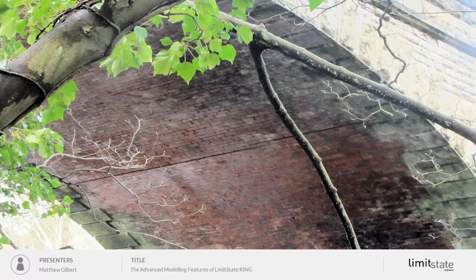but that's largely down to my assumptions on the level of backing in the bridge, and if I adjust those, then potentially I could get better correlation. So actually, when a bridge suffers a support movement, it's a very, very good opportunity to refine your model, because effectively it's a free test that you can use to help build a better model.